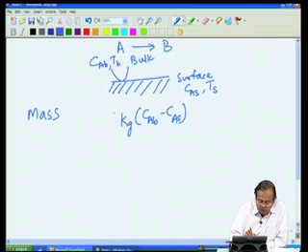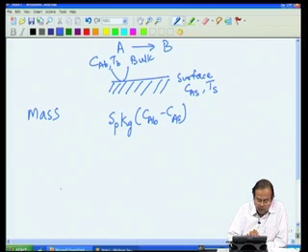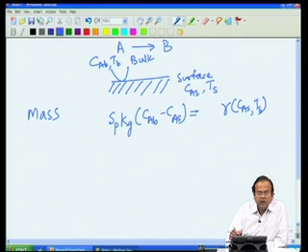So, let us say surface area per unit volume of catalyst, and this must be the same as the rate at which reaction is taking place on the surface. So, at these conditions CAS and TS multiplied by the volume, to keep the units consistent. So, this is my mass balance.